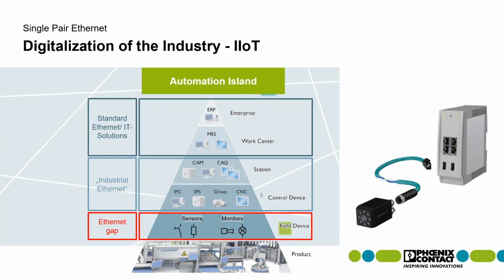It's sort of a democratization of the plant floor, and it's allowing sensors that previously were only communicating via field bus, whether that field bus was something like CAN in the automotive space, or a Modbus RTU, or DeviceNet or something like that, allowing them to use standard Ethernet and allowing the Ethernet revolution to sort of continue by getting those remote sensors on that same platform.